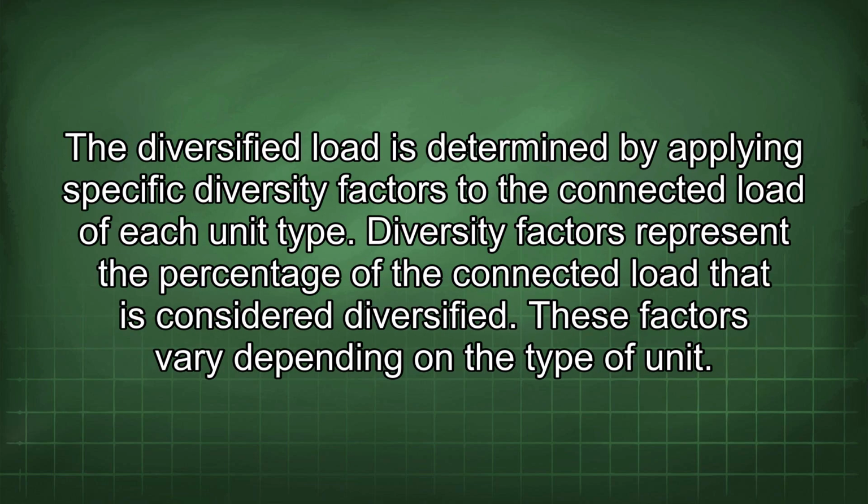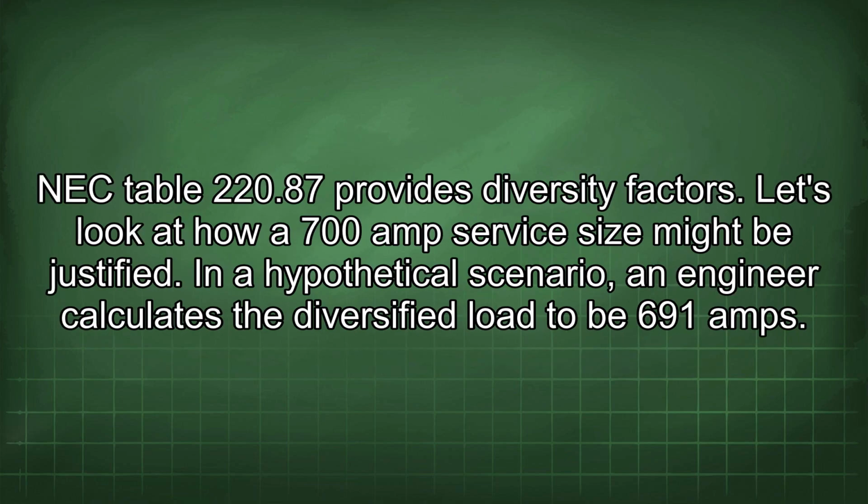The diversified load is determined by applying specific diversity factors to the connected load of each unit type. Diversity factors represent the percentage of the connected load that is considered diversified. These factors vary depending on the type of unit. NEC Table 220.87 provides diversity factors. Let's look at how a 700 amp service size might be justified.